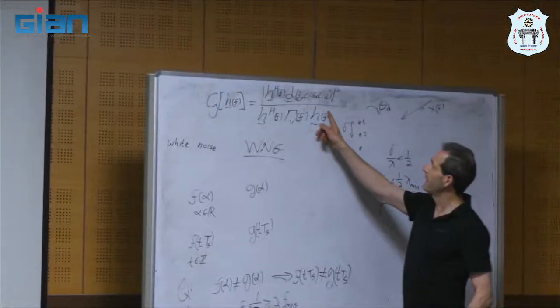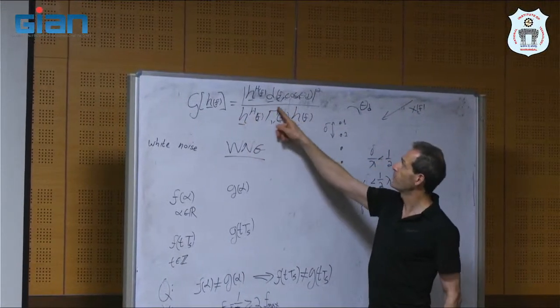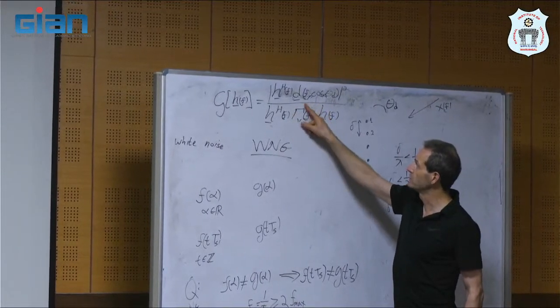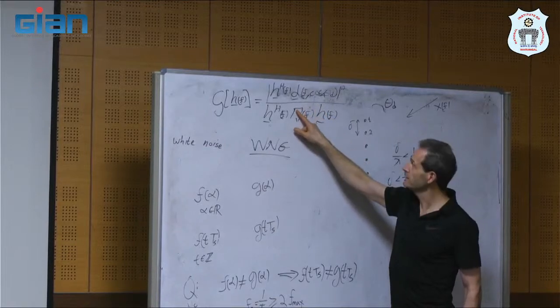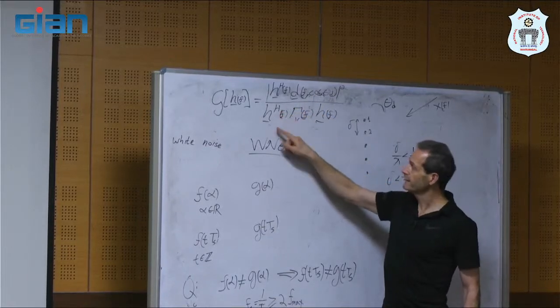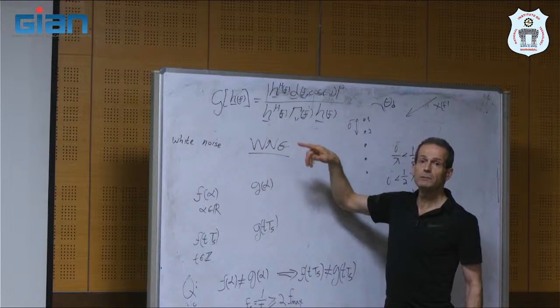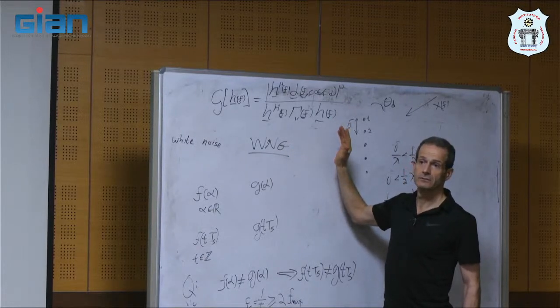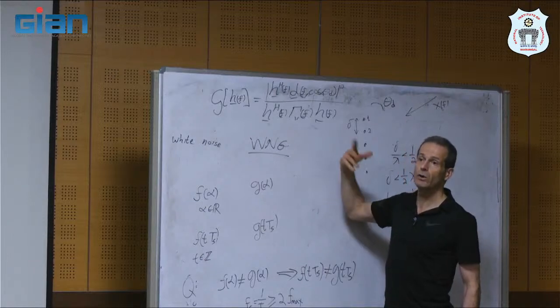So what we will do tomorrow, we will talk about robust maximum directivity factor, which means that we minimize this for the correlation matrix that corresponds to diffuse noise, but we also require that the white noise gain will be larger than a certain threshold. This will make it robust.